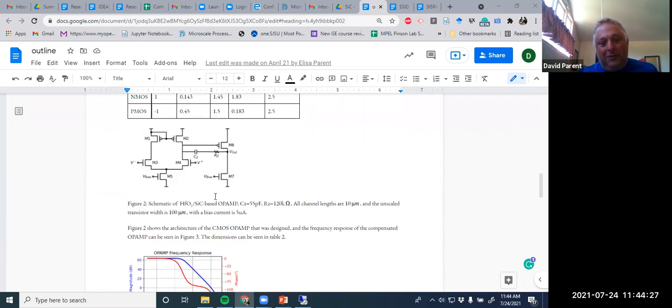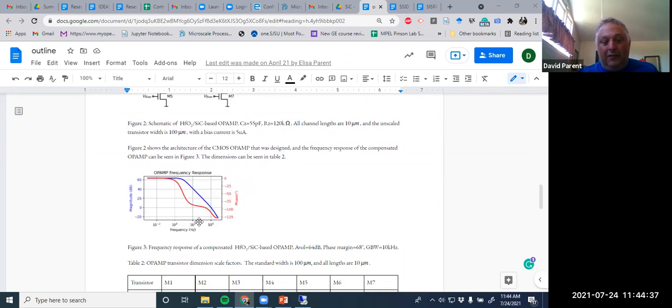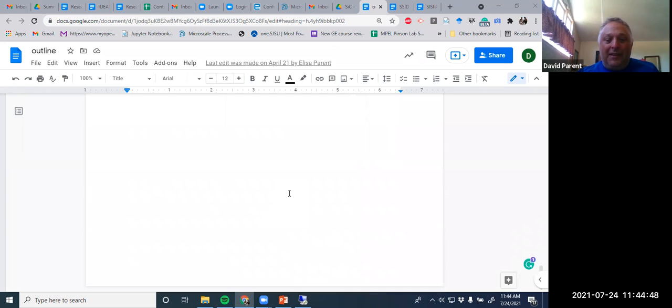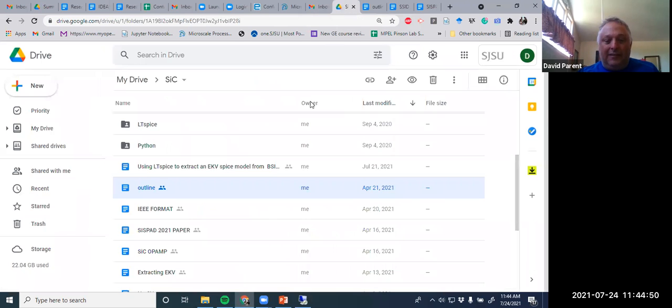And what we do is that op amps aren't inherently stable, and you have to add a resistor and a capacitor in the feedback path, right? So that it doesn't oscillate on you.